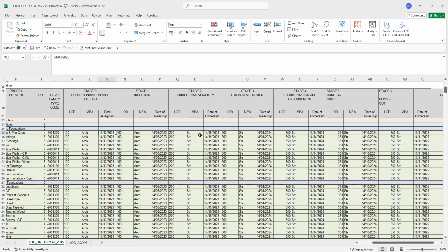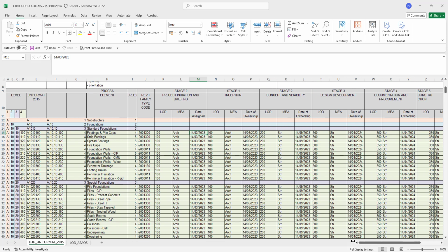Here you can see structural handing over onto architectural handing over onto structural at a specific date, and that would then become the model element author at that time. The ownership of the model will change, and the assignment of this across the disciplines is enacted according to, in most projects that I've seen, Uniformat 2015. It's not too detailed, but it's detailed enough for modeling purposes.